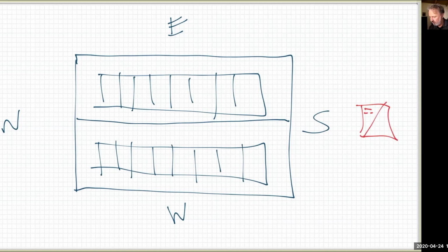What is very popular in residential inverters these days is what's known as dual maximum power point trackers. What that means is there's 2 inputs to the inverter so that each string, and a string is a series connection of panels, can be different. I don't actually have to have identical strings. I can have different numbers. So you might actually have 9 on one roof and 7 on another. That will work just fine as long as you're within the voltage window of the inverter on those strings.